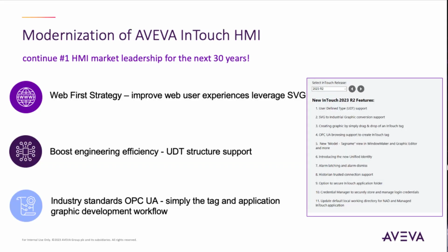And to begin, can you share some major highlights of the InTouch 2023 R2 release? Absolutely. So we've done a lot of things to InTouch HMI, mostly around improving the capabilities and the efficiency of how developers work. So some quick examples. We've added the ability to drag and drop UDTs and create tags, thousands of tags in seconds, to make it very efficient and error-proof. Connecting to OPC data sources is another way that you can bring in tags, again creating thousands of tags in virtually seconds.